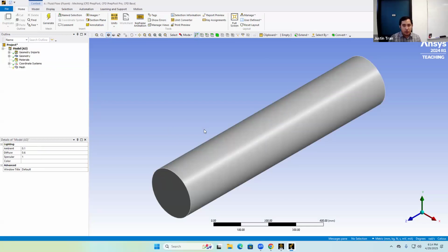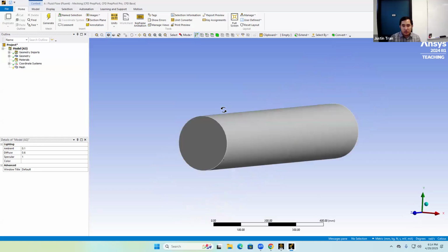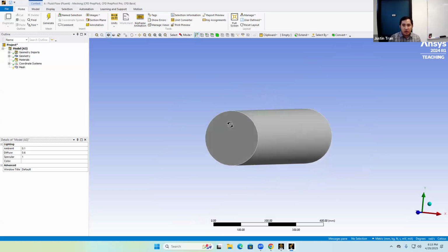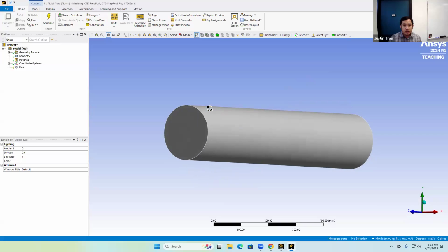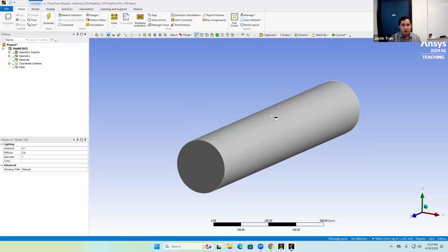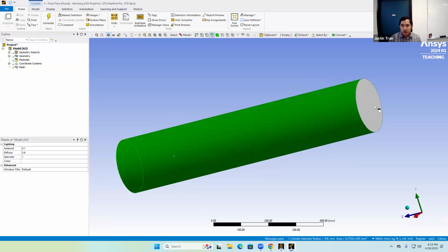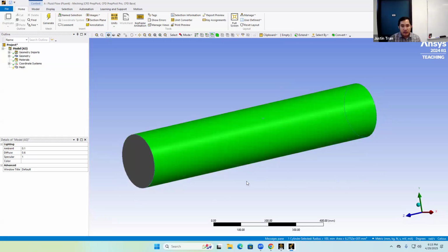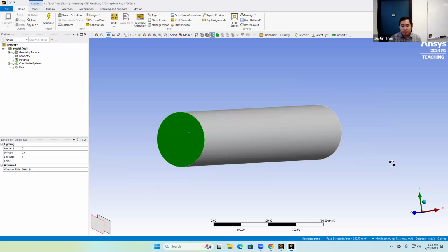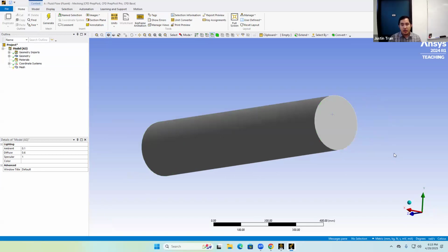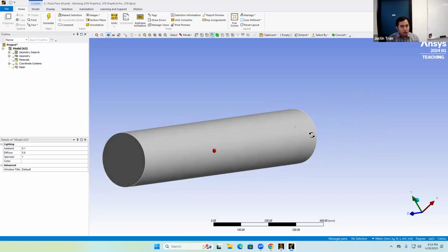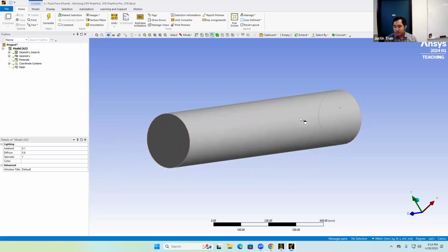Okay, all right, so you double click on mesh from ANSYS Workbench, and you should open up Mechanical, and you should see our cylinder here. If you select the exterior surfaces of the model, you'll see that there are 3 surfaces that we can select. We have the lateral wall, and we have both of the caps. Before we mesh, we need to create what are called name selections for each of these surfaces, just so that we can apply boundary conditions.